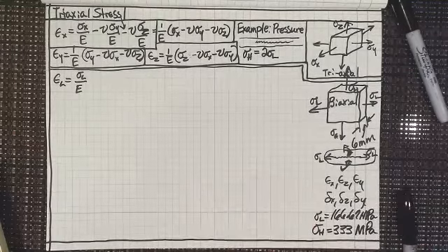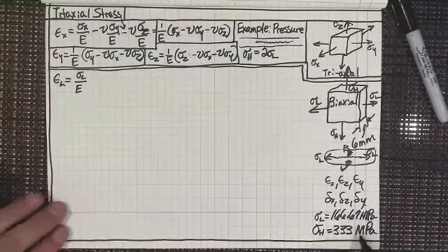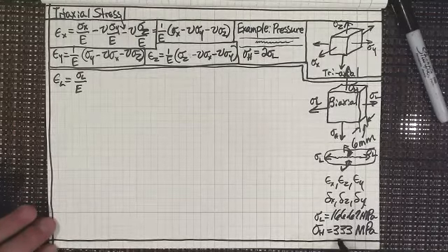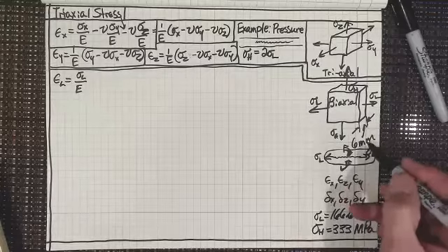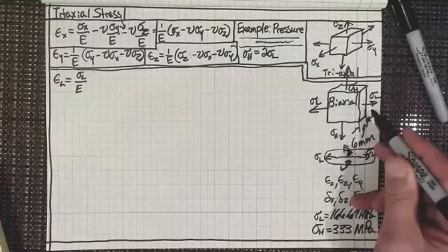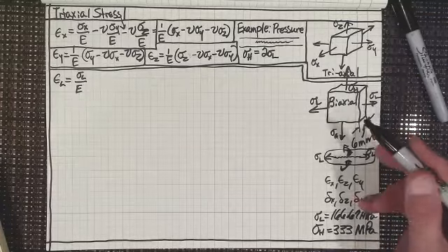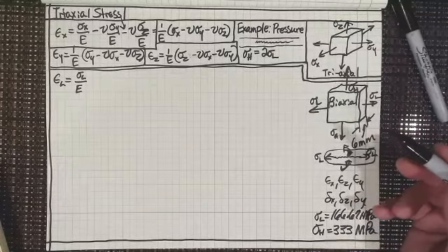All right. Now you're probably saying, "Wow, that's pretty high. That's close to the 400." Well, I'll tell you what you make a scuba tank out of is a pretty darn good steel alloy. So we don't really have to worry about it. A scuba tank could take this, and I'm giving you the non-safety factor. I mean, I say 6 millimeters, but really it's a centimeter, isn't it? Because it's like a safety factor 1.8 on a scuba tank. You don't want that scuba tank blowing up.